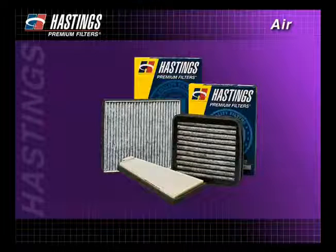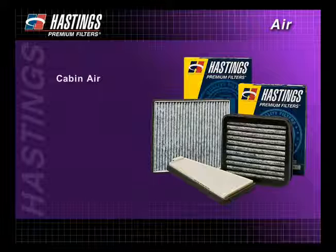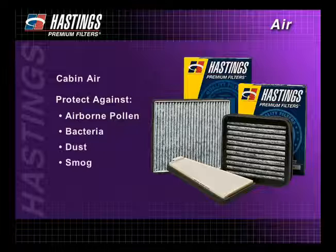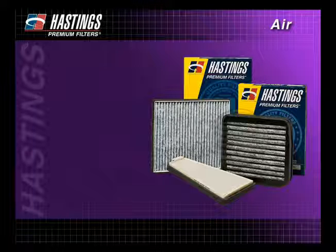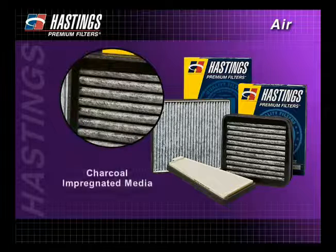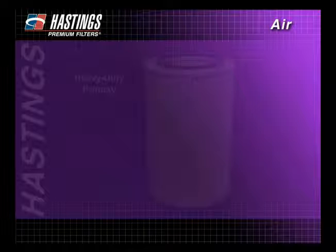Along with the automotive engine air filter, more and more automobiles, as well as heavy-duty vehicles, are coming equipped with cabin air filters. Cabin air filters protect against airborne pollen, bacteria, dust, and smog. They also reduce dust and dirt accumulation in the vehicle's interior through the heating and air conditioning systems. Some cabin air filters also contain activated charcoal-impregnated media, which has been treated with chemicals and heat to create specific odor control capabilities. Cabin air filters with charcoal media are able to trap noxious odors and gases.